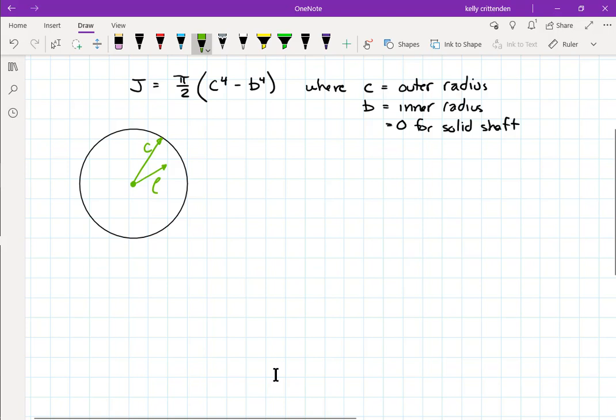So this will tell us about the actual stress, shear stress on the rod. So is it going to yield, or is it going to fracture, or anything like that? But it's possible, particularly if this shaft is pretty long, that it just twists without yielding even. So it twists, but it doesn't yield. Kind of like if something stretches, but it doesn't leave the elastic region, so it doesn't yield, kind of like a rubber band, but out of metal. It can do the same thing, and sometimes it twists so much that that's a failure.